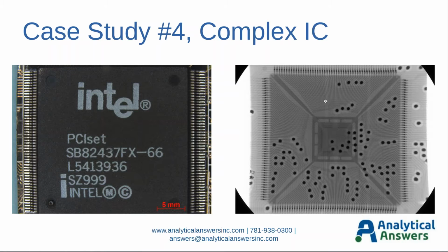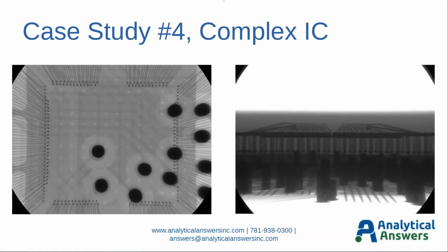Here we can also observe if there were any defects with the wire bonds going from the device to the external world here to the board. Just a higher magnification view of the integrated circuit showing those associated ball bonds to the circuit itself in the plan view orientation. We also need to understand, again, whether or not there's one or more of these devices present and what their orientation is in the Z-axis.